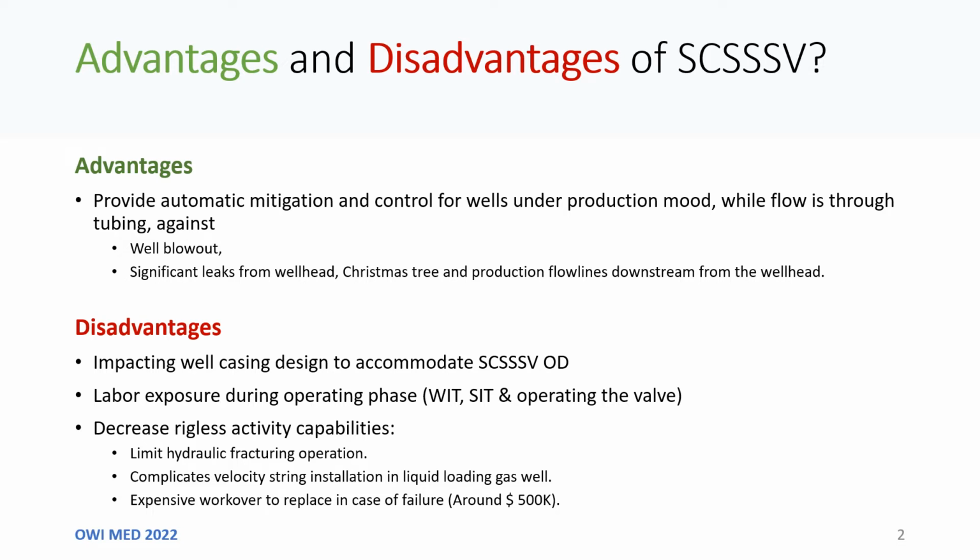Their disadvantages include impacting the well casing design to accommodate the surface control subsurface safety valve outside diameter. They cause labor exposure during operating the subsurface safety valve, during maintenance, and during the wellhead integrity test. In addition, it limits the capabilities of regular activities.